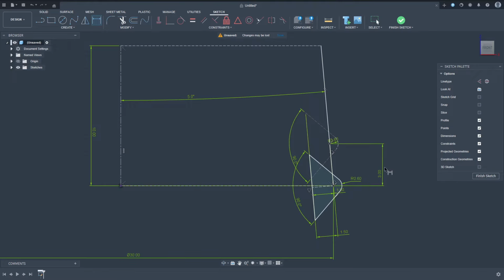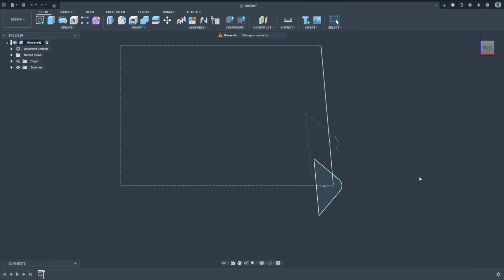As you can see, the profiles overlap, which is intended in this case. Really, the depth of the profile does not matter, except that it should overlap when offset by the pitch, so I decided to reduce it a bit. Then I finish the sketch. The next step is to create the guide curve.